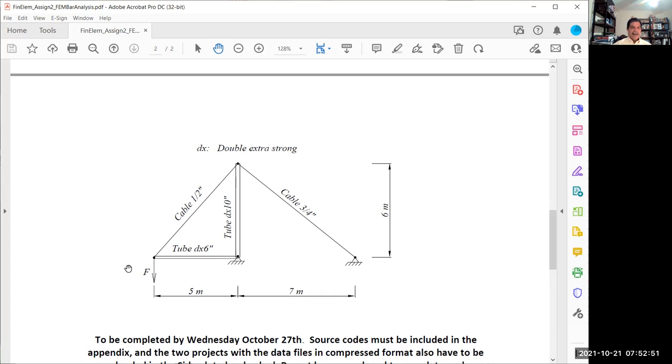You want to know what's the maximum force that you can apply here so that nobody has a stress larger than 235 divided by 125. Any suggestion, people? How can we do it? We can apply a force minus the yield point to see and then see the value of the displacement and compare.